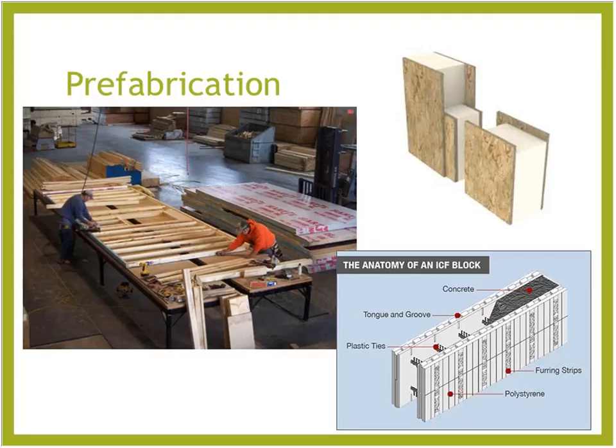And again, those get designed in a shop, and then they get assembled on site by a builder. So again, reducing waste, having completely air sealed from an energy standpoint, reducing all thermal bridging that we talked about in the energy category. So lots of benefits for using SIPs. And then if you're concerned about the foam in the SIPs, they actually have structurally or prefabricated cellulose SIPs now. So they have a cellulose sandwich inside of them instead of foam. So you can check those out.